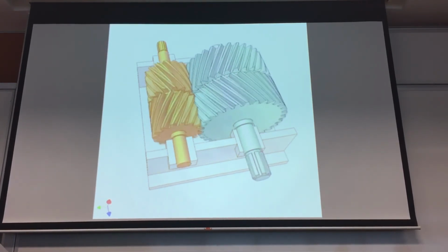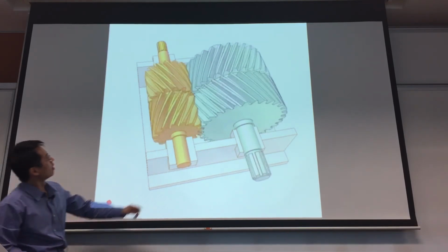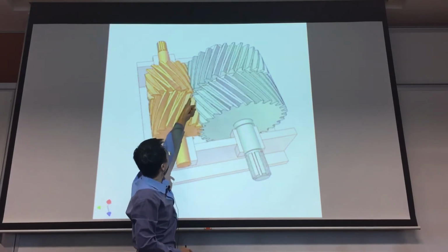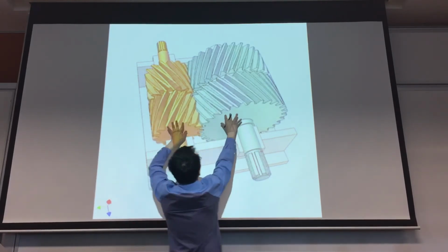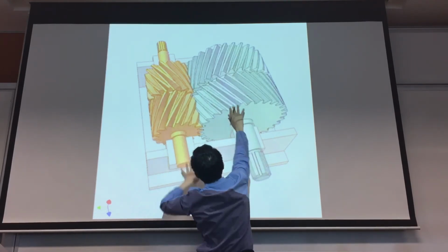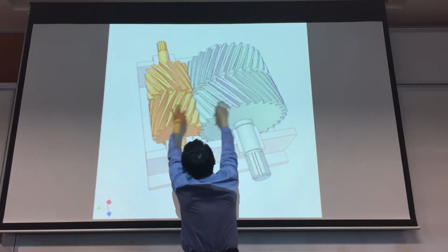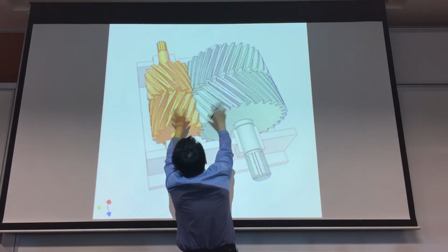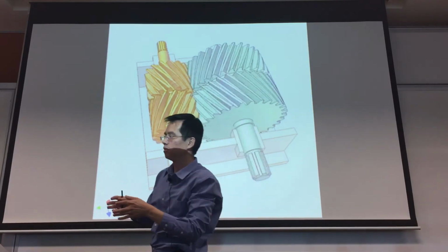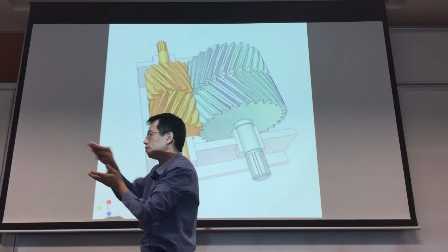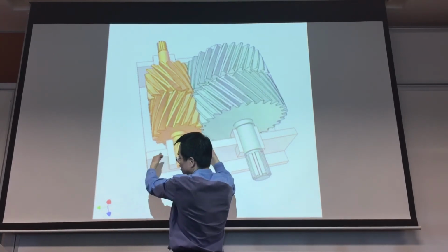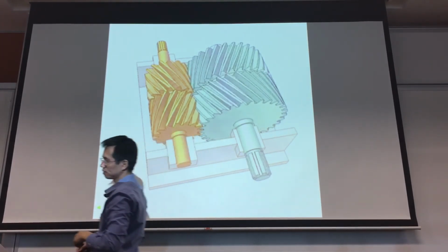So you can see it's just rotating. For any point of contact, it's only one point, and then it moves through. Had it not been chevroned in that way, if let's say just only this part, then these two gears are going to move away from each other. So if you have herringbone, that means it will stay over there, and hence the bearing system that's supporting it does not need to accommodate that axial loading. It's only the radial loading that's necessary, but not the axial loading.